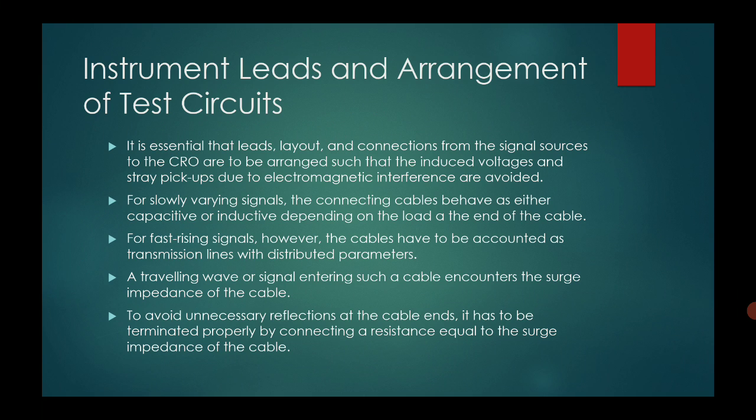The instrument and the lead arrangement of the test circuit. So we are talking about how the leads and connections are arranged for the test circuit. It is essential that leads, layout and connection from the signal sources to the CRO are arranged such that the induced voltages and stray pickup due to electromagnetic interference are avoided.